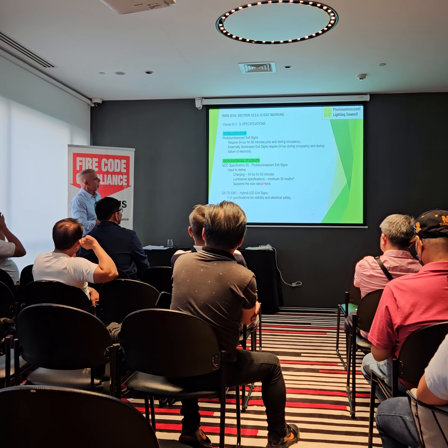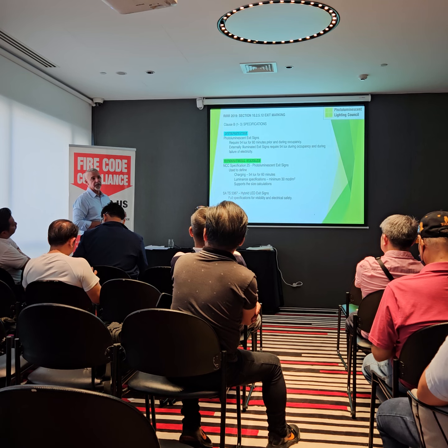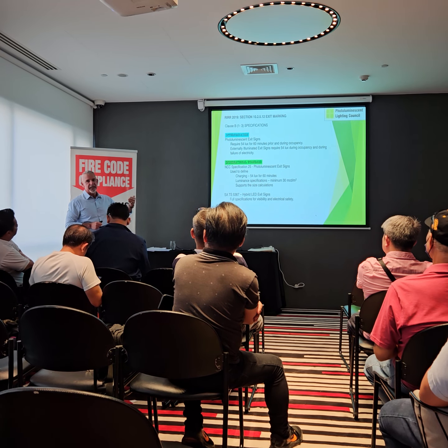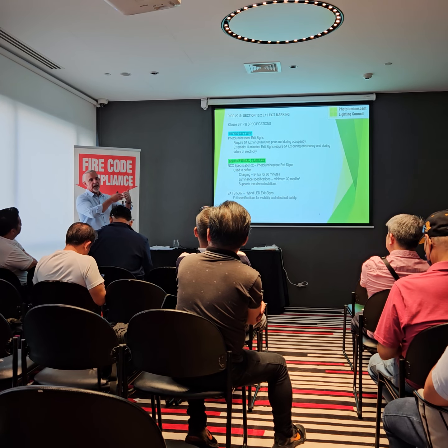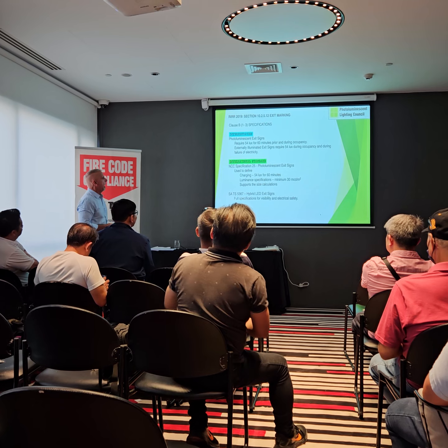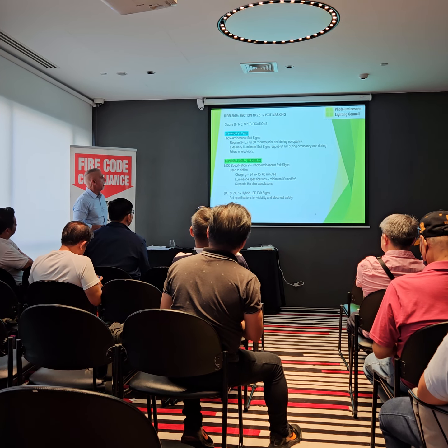For these signs, the recognised minimum is 30 millicandelas. And remember, the reason for that is that you don't just have to see that the sign is there, you have to be able to read whatever is on the sign. So that's why that luminance requirement is higher.